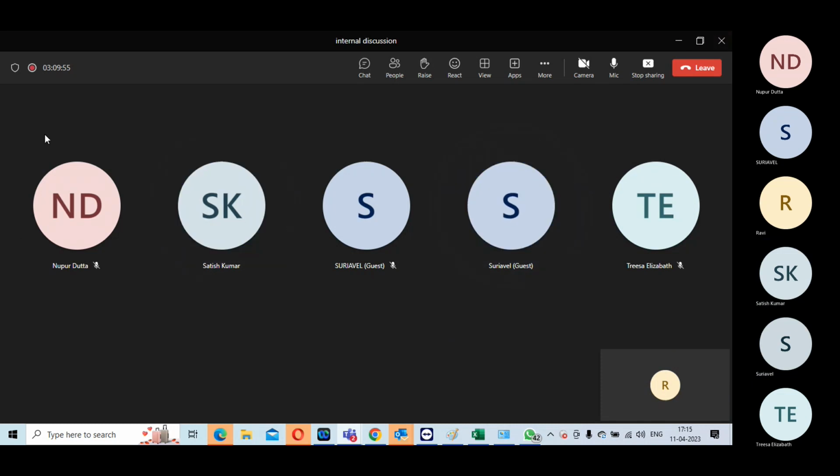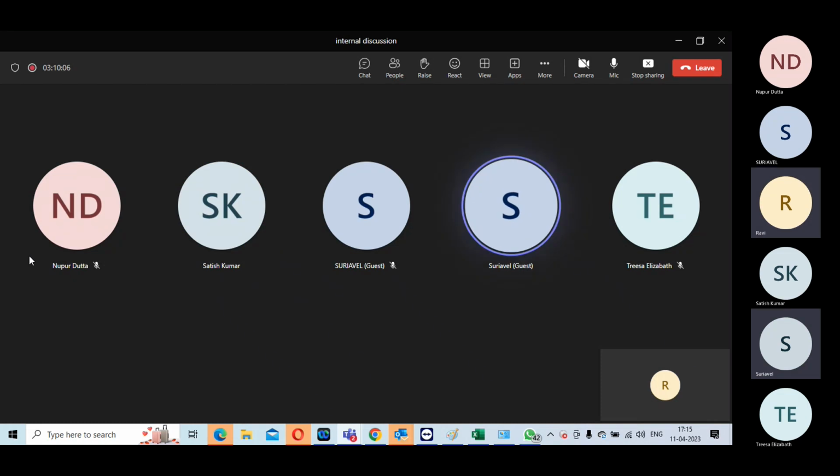Sir, one more last question. Is skew grouping mainly done to reduce the latency? No, a skew group is basically created to isolate different clocks from balancing each other. You create another skew group so that you don't really care about clock balancing between these two groups.